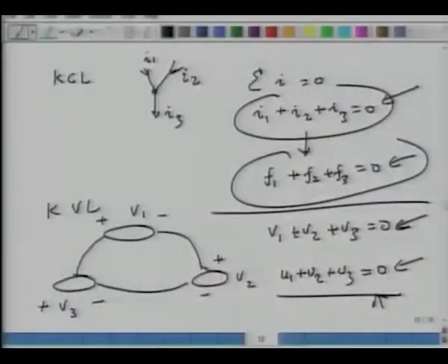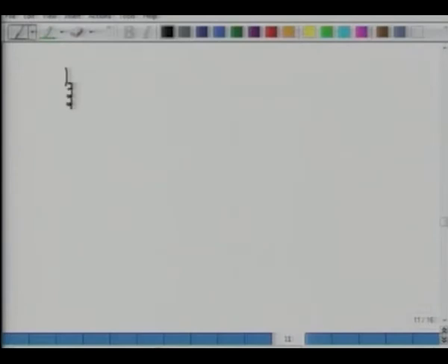So let's say I have a very simple spring mass system. The mass is mm. The spring has a stiffness of K, or a compliance of Cm, and it's being excited by some source velocity. So let's say I am interested to find the velocity of the mass. In other words, if I map it to the electrical world, I want to find the potential difference across the mass, right? Because velocity is mapping to voltage.